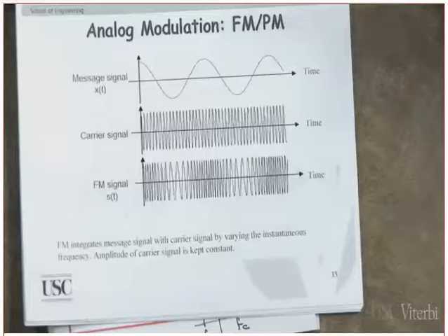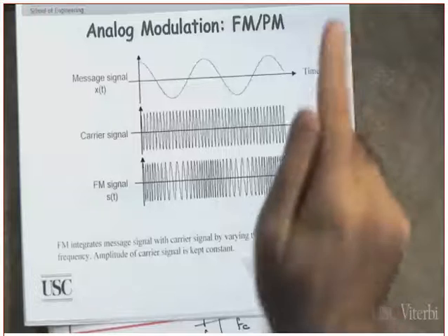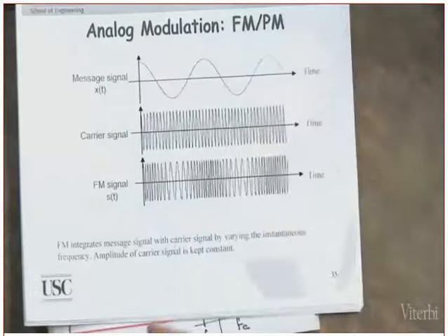But intermodulation components, especially the third order intermodulation components, we don't know what that means yet. We'll get to it shortly. They might result in components within the band. It might even be within the desired channel. You might say, okay, so I filter it. You filter it, you are filtering the channel itself. Did you get my point or not? Okay, good.